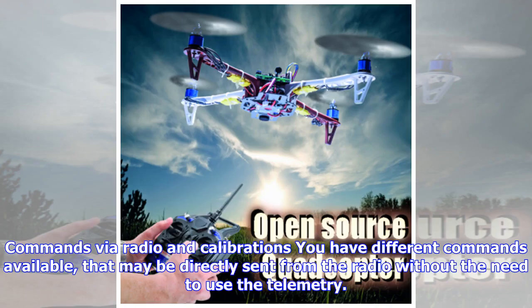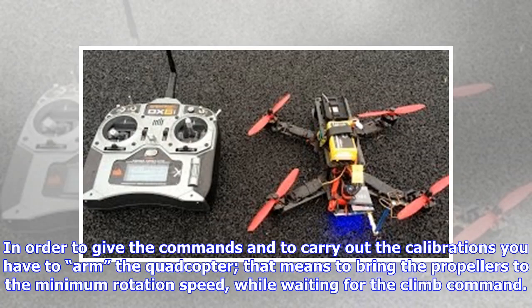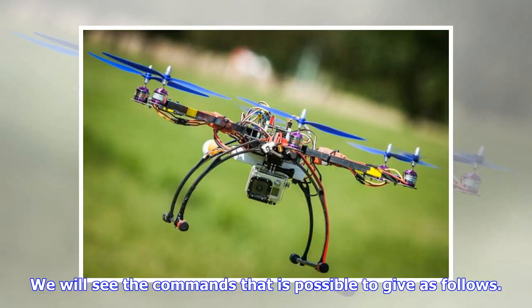You have different commands available, that may be directly sent from the radio without the need to use the telemetry. Once the quadcopter has been powered, the propellers remain still and the motors are not powered, they are therefore unarmed. In order to give the commands and to carry out the calibrations, you have to arm the quadcopter. That means to bring the propellers to the minimum rotation speed, while waiting for the climb command. We will see the commands that it is possible to give as follows.